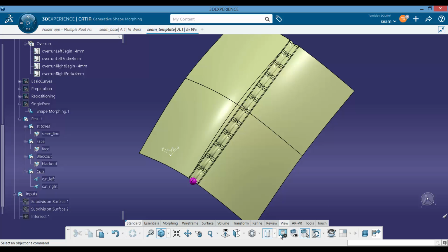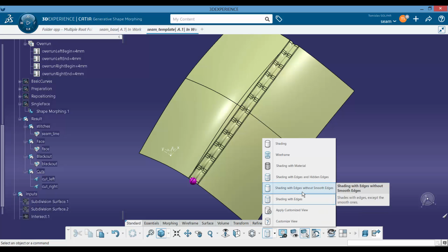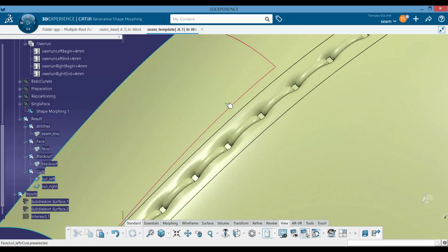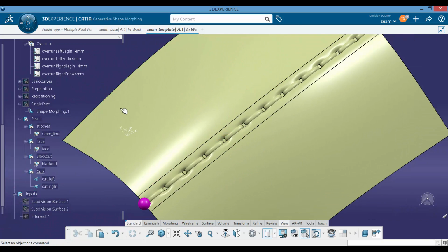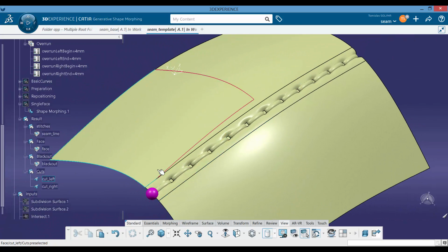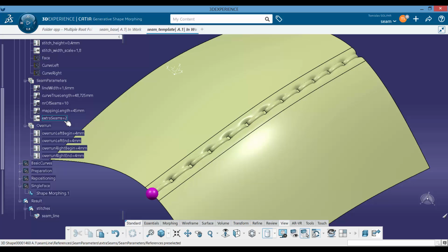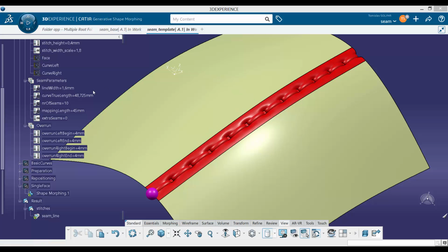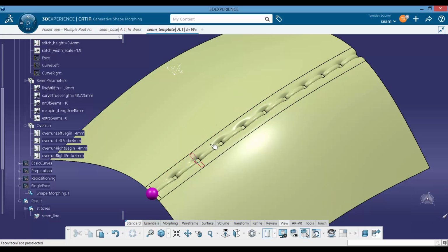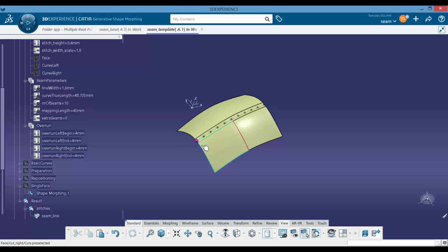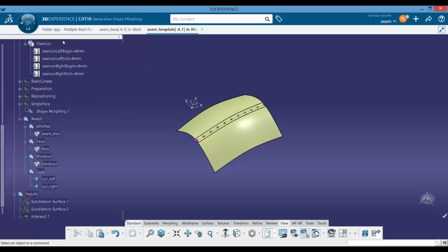And yes, we can see as well here that if we simply remove this edges with smooth edge, if you take a look, we will see that we have 12 elements, even though this line was 50 millimeters, so 10 elements were optimal number. This was because we had these extra elements, which we can in this case put on 0 and update our models just to prove that the model is actually stable.